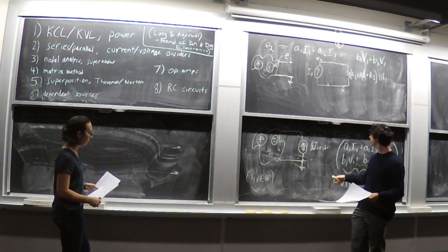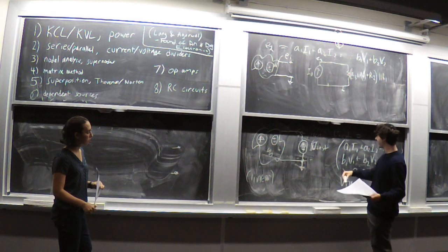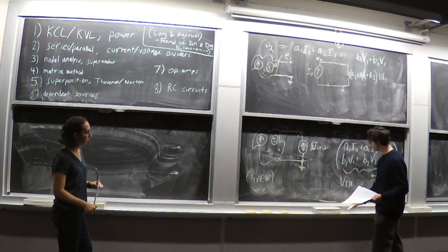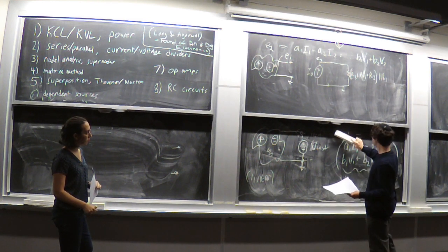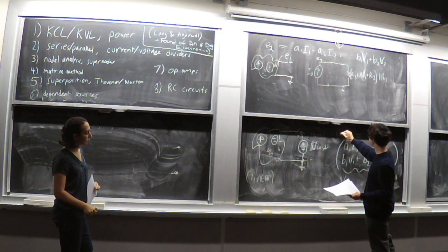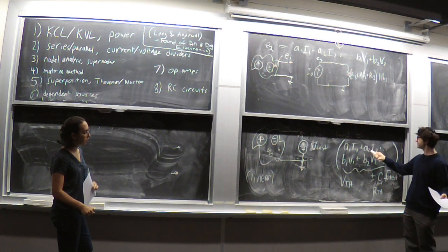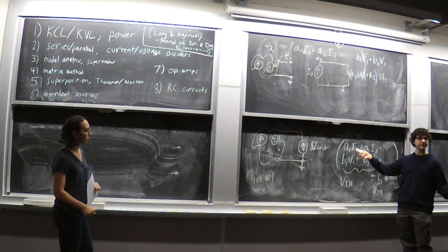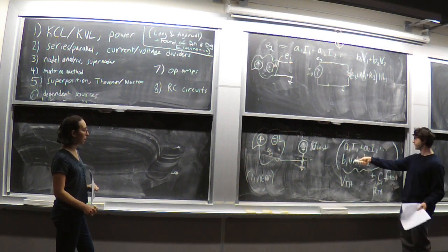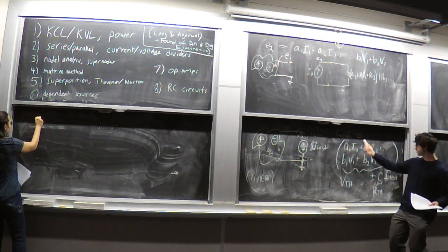And so when we do it this way, the same principle applies, right? The response we're going to get, this current we're going to get, is going to be proportional to all of those independent sources inside the circuit, just like V-test was before. One thing to note is now, right, the A's are going to be unitless because we're solving for current, whereas the B's now are going to have units of conductance so that we're converting voltage to current.